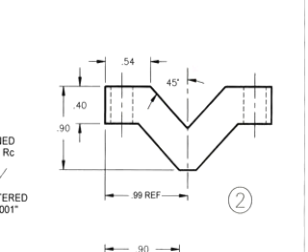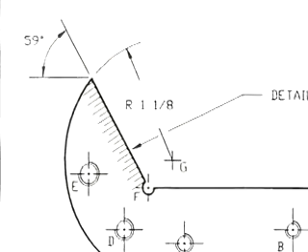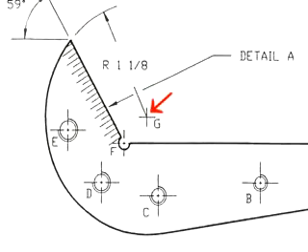Sometimes extension lines aren't required. And sometimes a center line can be used as an extension line. Sometimes they seem to extend from nothing, as is the case with this extension line here, which is actually the offset extension of the project's horizontal plane. Sometimes they're curved, as is the case with this extension of the 1 1/8 of an inch arc. And this center spot here is actually another way of showing a type of extension line.